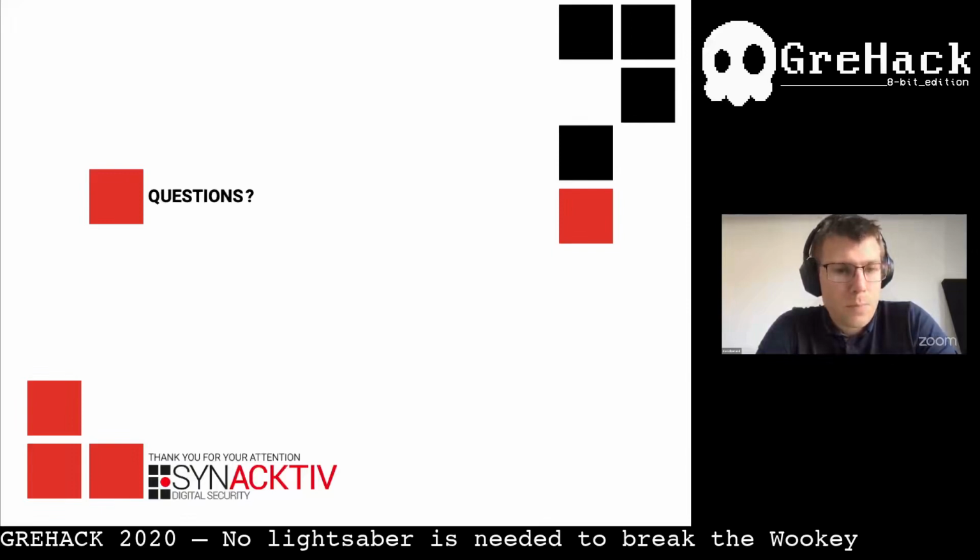Okay, but is this a limitation of the material you need to reset, or why do you need so much time? Because each try takes time. You have to reset the board, try a parameter, wait a little to be able to check if the JTAG is enabled or not. So each try took more or less a second. So it took a lot of time to reproduce all the parameters we have to cover.